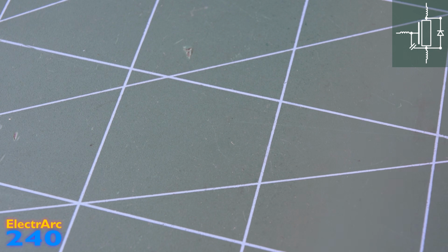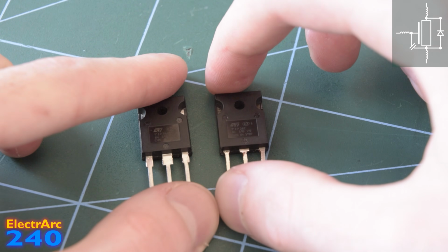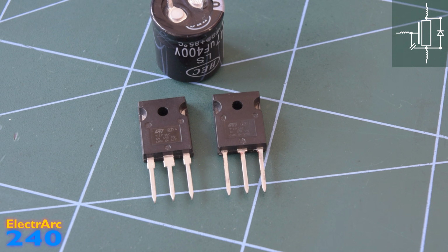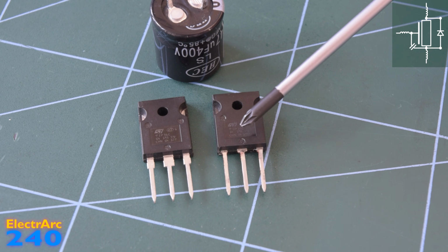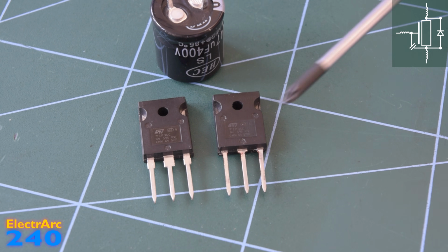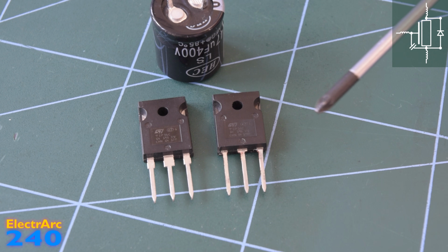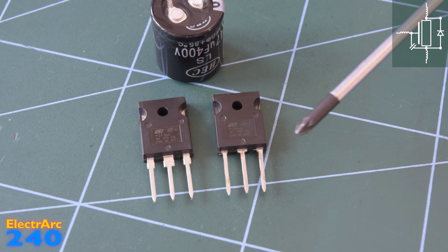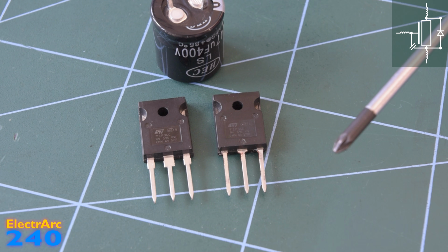In the case of the humble half-bridge, which is 2 MOSFETs and a DC capacitor, this inductance is referred to as the loop inductance, and it includes the source and drain inductance of both MOSFETs, as well as the inductance of the capacitor and of the circuit between them. This is something that's really important to minimise in a half-bridge if you want to switch fast and minimise your losses. And this is where modern surface mount components really come into their own.